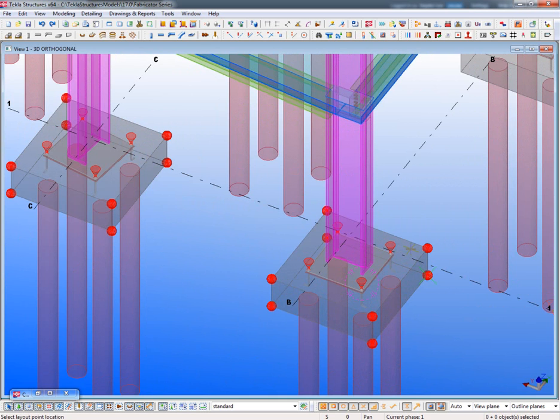That actually happened on a project that I worked on, and they were crooked, so just creating oversized holes didn't really work. They had to bore out different locations for the holes in our base plate, but we were able to get that information relayed back.